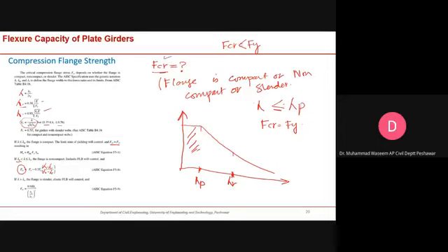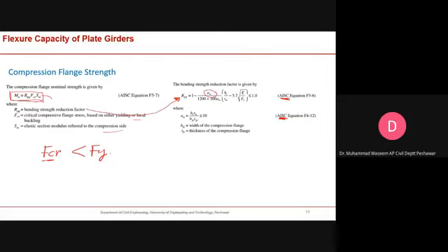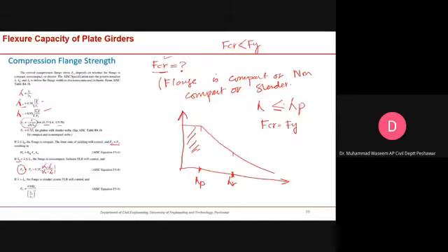Okay, in order to evaluate this limit state, you need this one, and in order to calculate this FCR, you have to see whether your flange is compact or non-compact. Okay, if it is slender, then you have to use a different formulation in order to calculate this FCR. Okay, is it clear? Yes, sir.